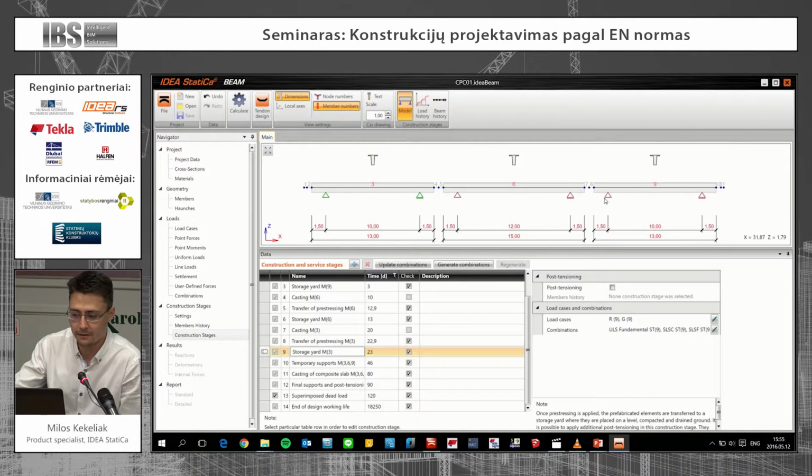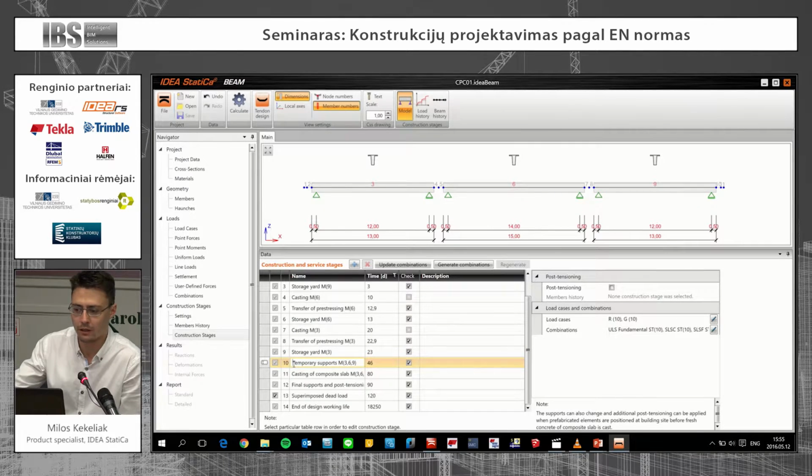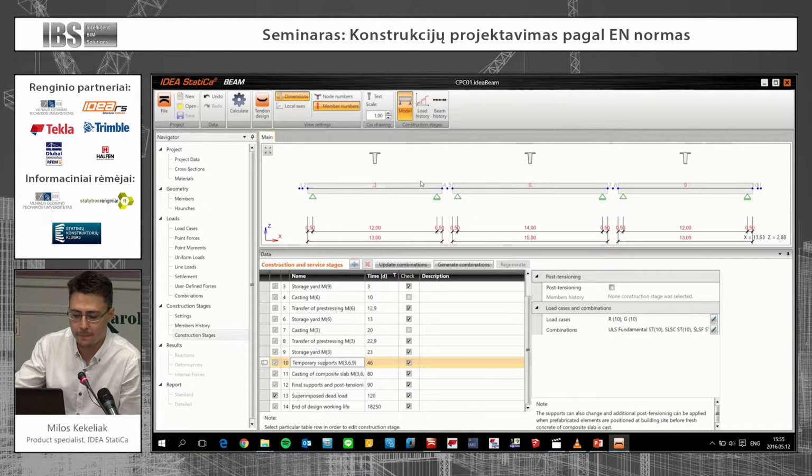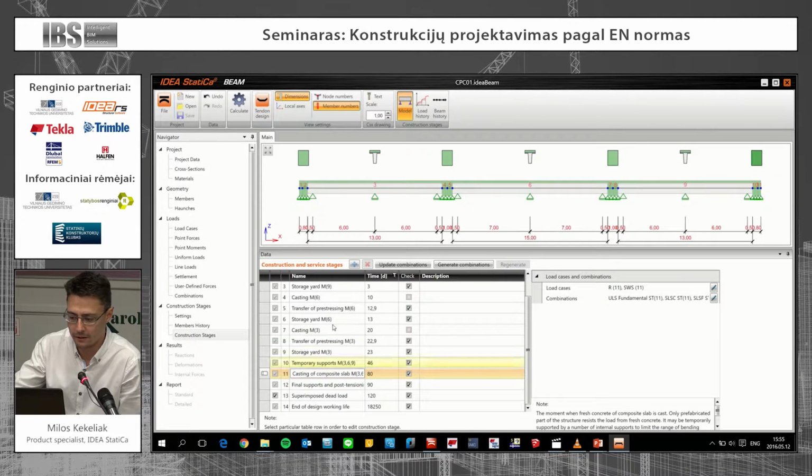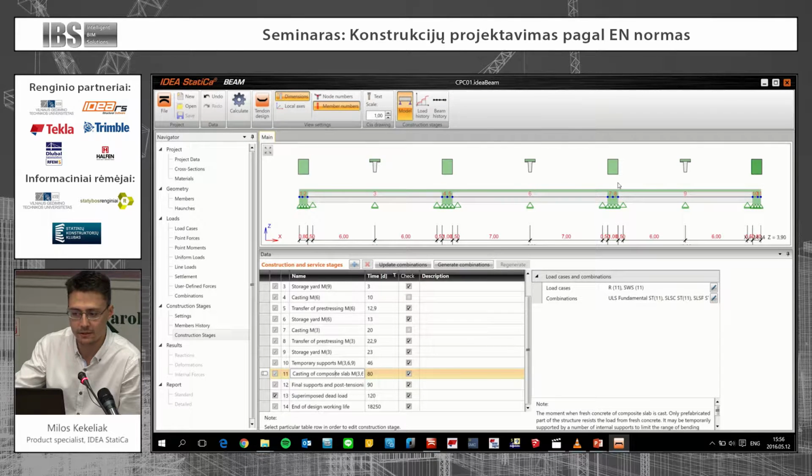And these stages that I presented right now are stages only till the stage of prefabrication, transportation on the construction stage. Okay? So in the stage when they are moved to the construction site, the structure is placed in position, and there are only beams. In a further stage, there is a stage of casting of the composite slab. You can see that the green elements represent the casting of the composite slab and the diaphragms about the supports.